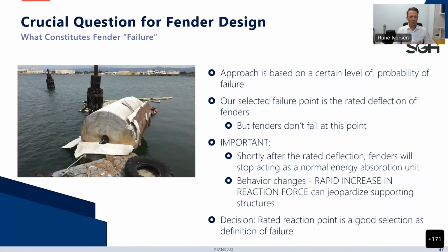So I've talked about failure of the fender system, and an important thing to think about is what constitutes actual fender failure. So our selected failure point for the fenders is the rated deflection of fenders. I think we all know that most fenders don't actually fail at this point. But the important thing to remember is that the fender is not a standalone structural system. It actually interacts with the wharf or the structure that supports it.